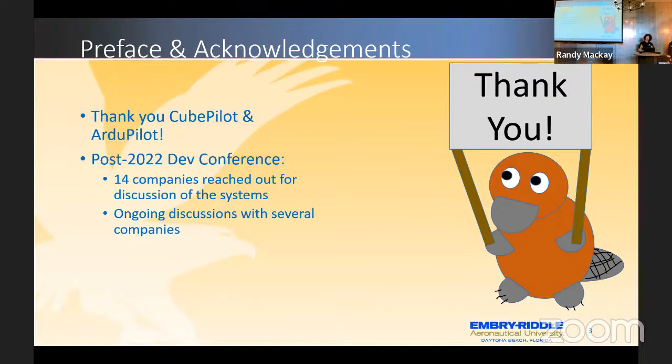The problem we have with our highly autonomous or automated systems with multiple state machines at multiple levels is that you can get a situation, and it can be crazy, where one flight computer is trying to land, another flight computer is trying to fly to waypoint 3, and the other flight computer is trying to fly to waypoint 7. Or the integrators on all 3 lanes diverge. And then you switch over and you get a bad day. So that's in part being handled by a cross-level database, with those key items that it keeps. But we need to include this in our architecture, and that includes our software architecture and our hardware.